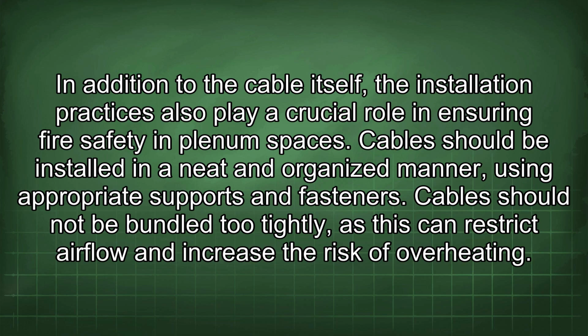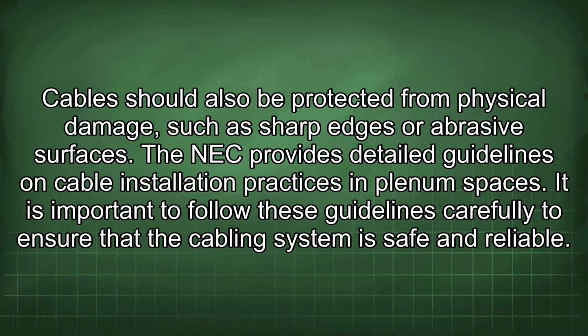Cables should not be bundled too tightly, as this can restrict airflow and increase the risk of overheating. Cables should also be protected from physical damage, such as sharp edges or abrasive surfaces. The NEC provides detailed guidelines on cable installation practices in plenum spaces. It is important to follow these guidelines carefully to ensure that the cabling system is safe and reliable.